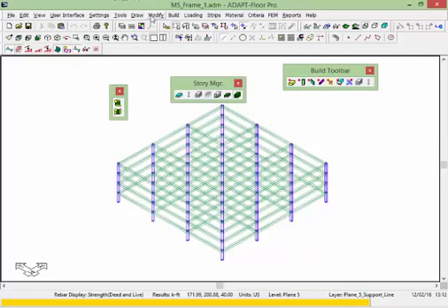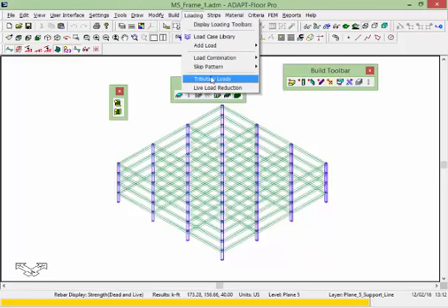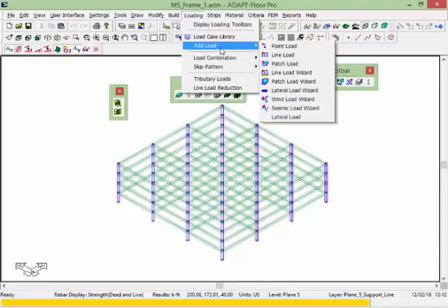If we go to loading and then select the option for add load, wind or seismic load wizard, these two wizards are related to the inclusion of slabs and frames that include slabs or walls, columns, and so on. You could still have beams, but the prerequisite is there are nodes relative to shell elements, not frame elements. They would also include nodes for frame and shell elements, but we have to have shells. In this case, we're constraining that and saying we're not going to have any shells. So that requires us to manually add lateral loads to this frame.